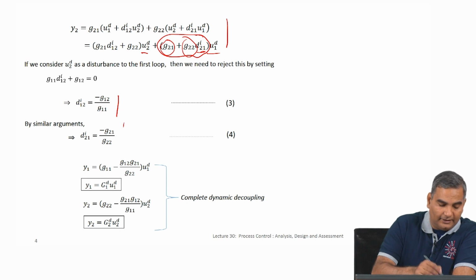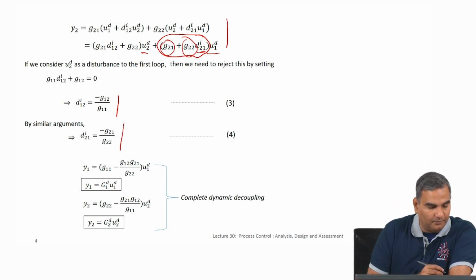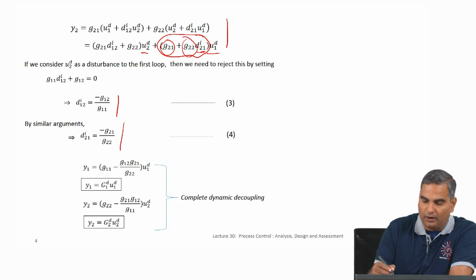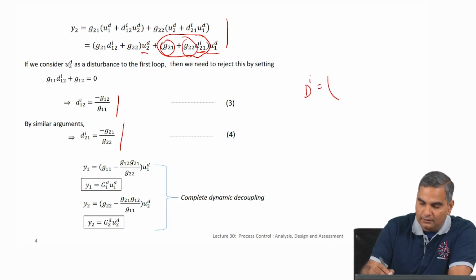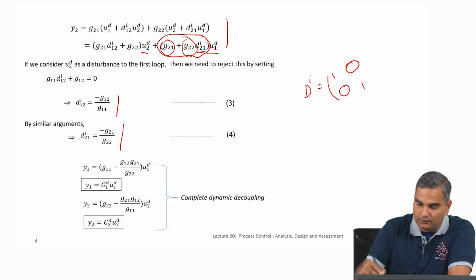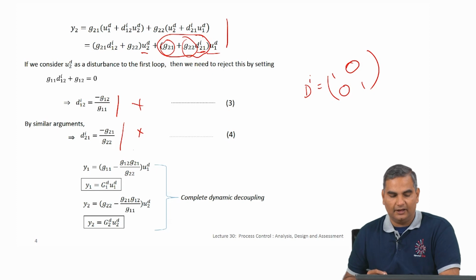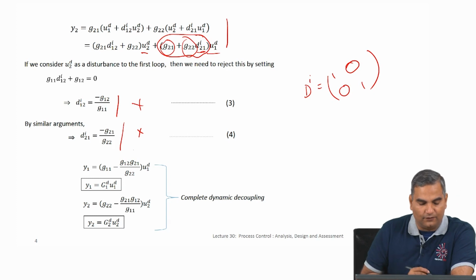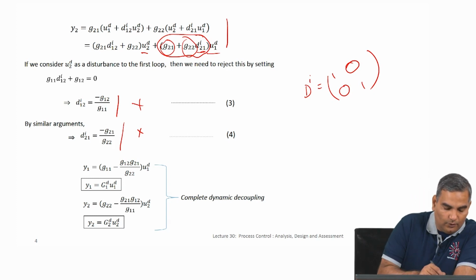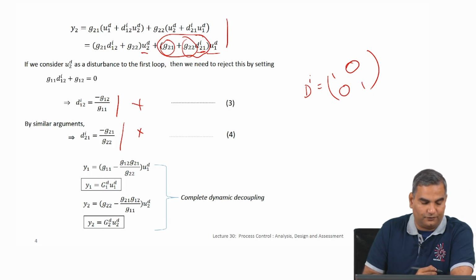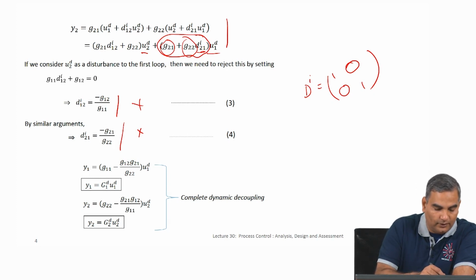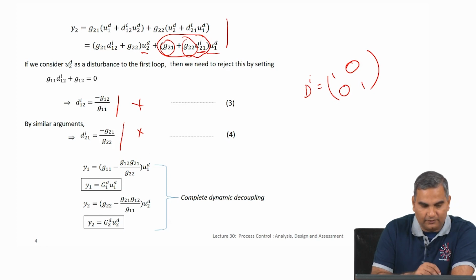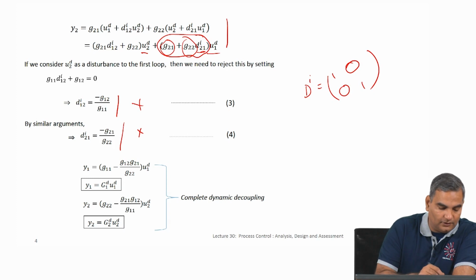So, from this I can get these two decoupling elements, which I put into this overall D_i. I have 1, 1, and this one I have computed, this one also I have computed using these two equations. Now, I have an input decoupler. If you simplify this in terms of transfer function only for u1 decoupled, you will get y1 equal to g1, a slightly different transfer function from before. Initially if it were u1, this would just be g11, but because we are going to correct for the effect of u2, this transfer function becomes this transfer function. Similarly, this transfer function becomes this transfer function.